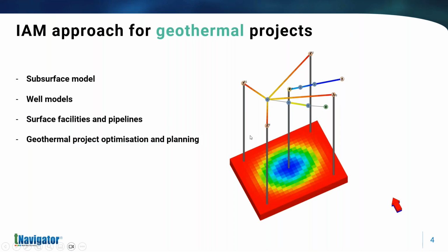So talking about geothermal and IPM, the idea is to connect all elements of the system into one model. We have our surface model, and we can also do the well modeling in quite some detail. Today we'll try to focus on how we can use these well models for optimizing the completion, calculating the temperature, and analyzing the well performance in general, for the long-term forecast and for short-term optimization.